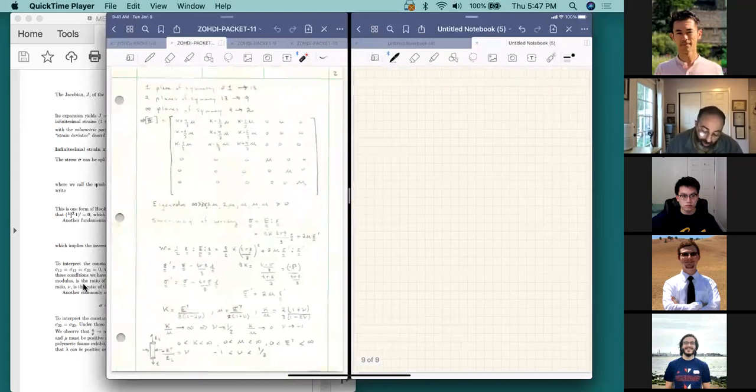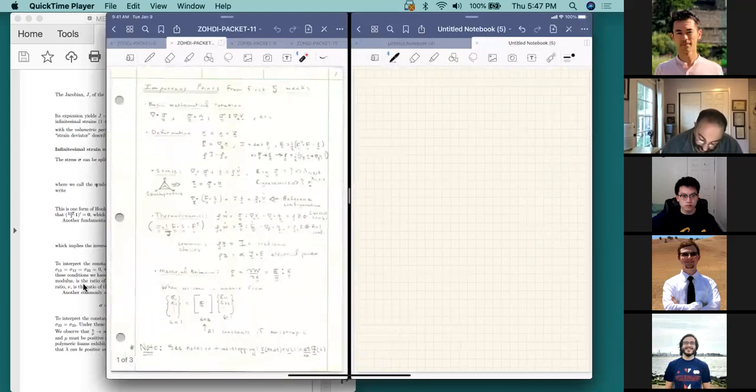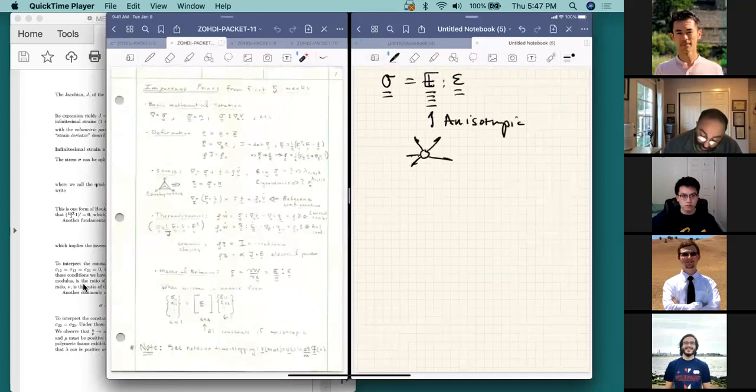At that point, we went into the whole idea of constitutive laws, and the constitutive law we needed to start out with is the so-called linearized elasticity. Linearized elasticity basically starts like this, but this is potentially fully anisotropic. Through several arguments, we find that if the material is isotropic, meaning that if I pull on it in all the different directions, things simplify.